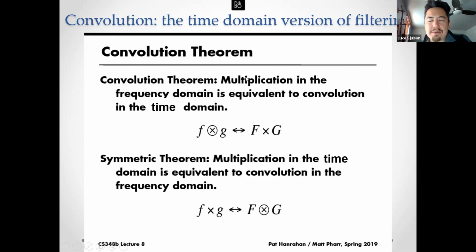So you can do filtering in the frequency domain. You can conceptualize filtering in the frequency domain the way that I just showed it, but you can also do filtering in the time domain. And the key idea here is this operation called convolution.